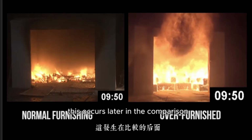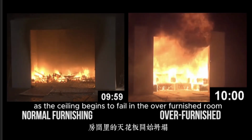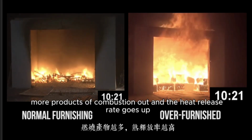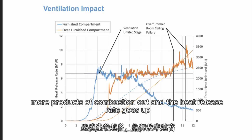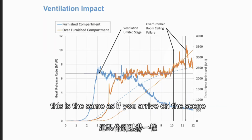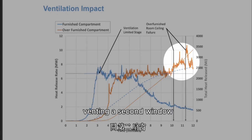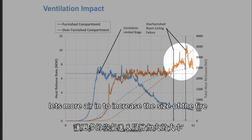This occurs later in the comparison as the ceiling begins to fail in the over-furnished room, allowing more air in and more products of combustion out, and the heat release rate goes up. This is the same as if you arrive on the scene with fire out of one window. Venting a second window lets more air in to increase the size of the fire, so coordinate water on the fire to stop that fire growth.